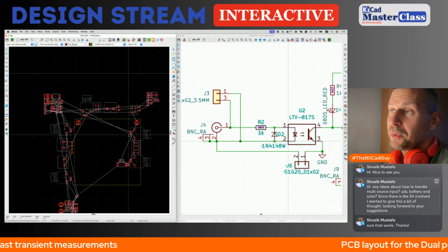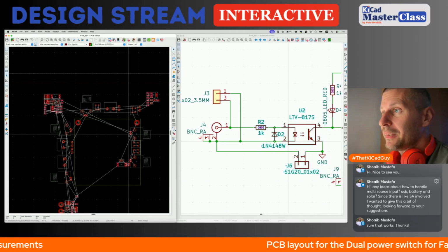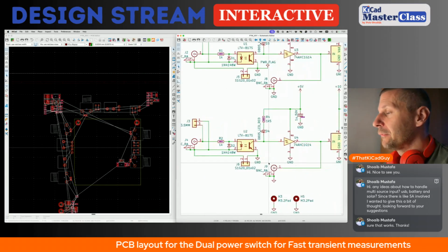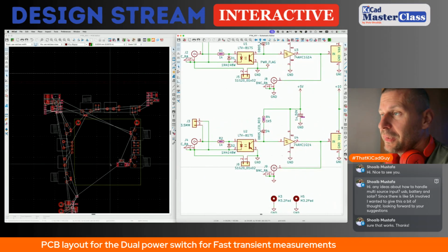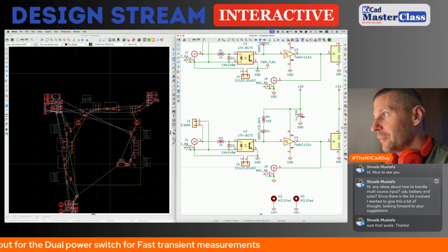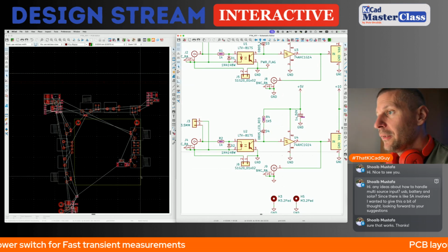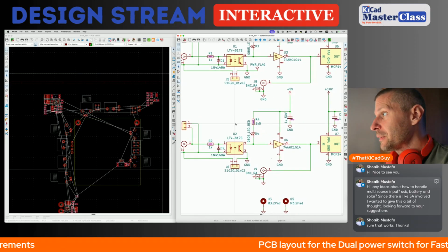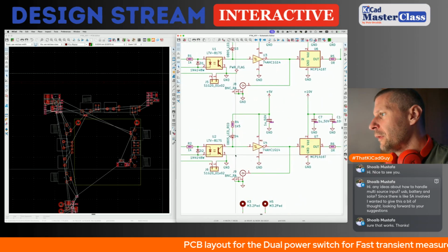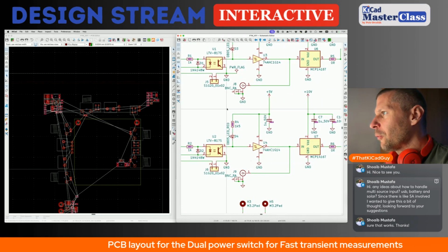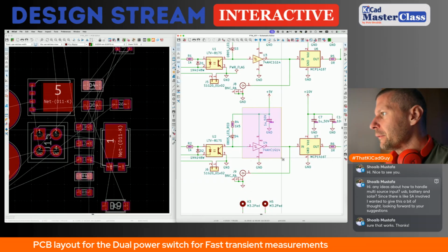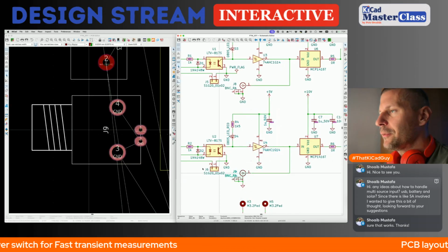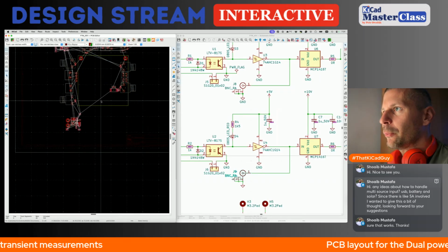That's the optimal size, I think, because I need some stability on the desk, but if it works, the PCB can be even smaller, because 70 by 70 or 70 by 80 can work as well. So now we have the LED, the Schmitt buffer, and another BNC, which is located on the opposite side.